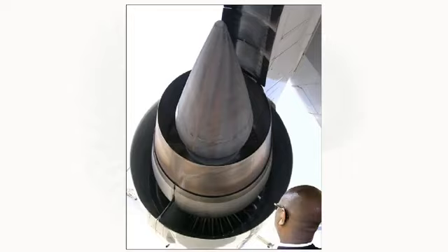Alternatively, if your starter crew trust you, and if it's safe for them to do so, you could direct them to the rear of the engine and, having selected relight, ask them to listen for the asynchronous ticking noise which two high-energy igniters make when they're feeding spark to two serviceable igniter plugs.